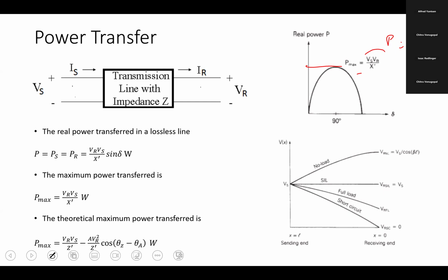So in this case, Z equals jXL, and V squared can be split into sending end voltage times receiving end voltage divided by Z. Maximum power happens when the angle is at 90 degrees. When it is below or above that, you will see the power curve here and here. And that power curve is not allowed to go very low, here or here. That is what it shows.